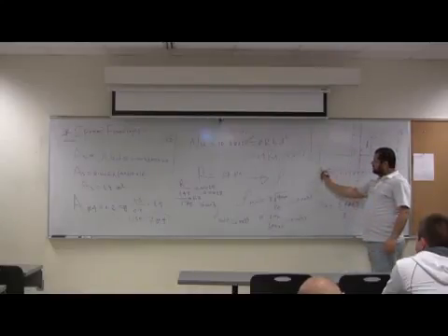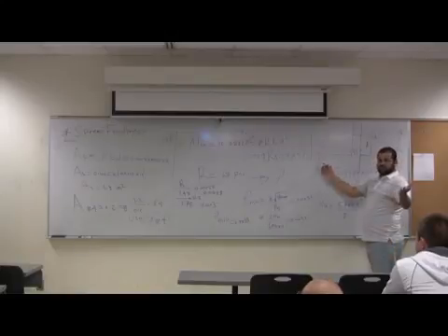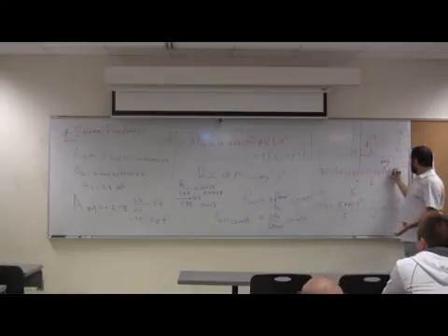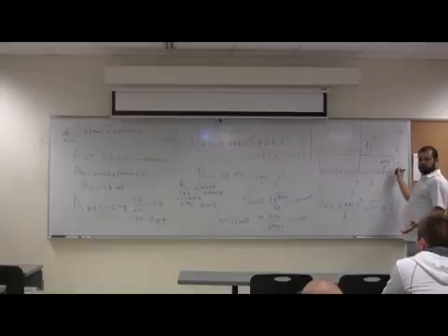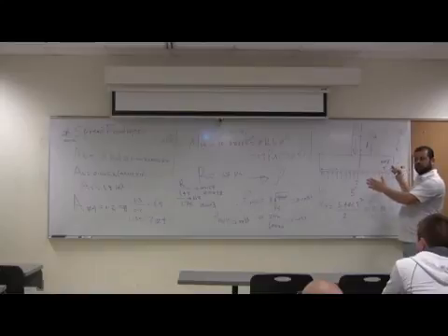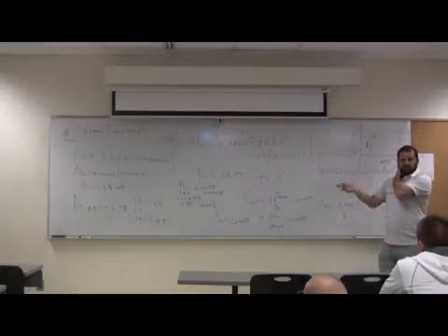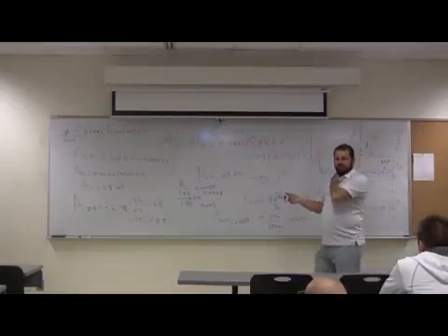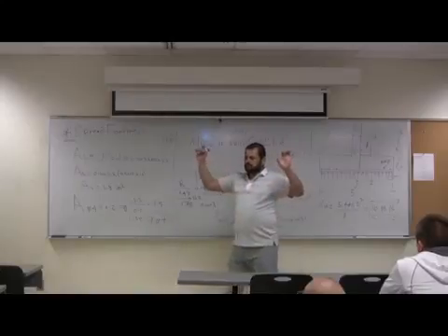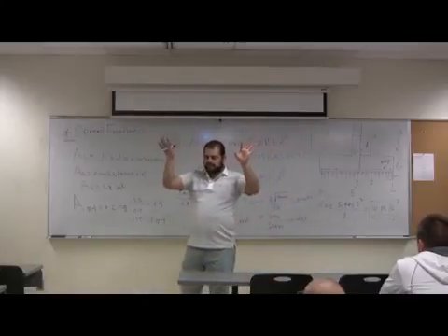Can I get the first bar closer than 3 inch to this side? No, 3 inch is gone. So 5 minus 3 leaves a distance of 4.5 foot times 12, in inches. When you put 7 bars, how many spacings do you create?